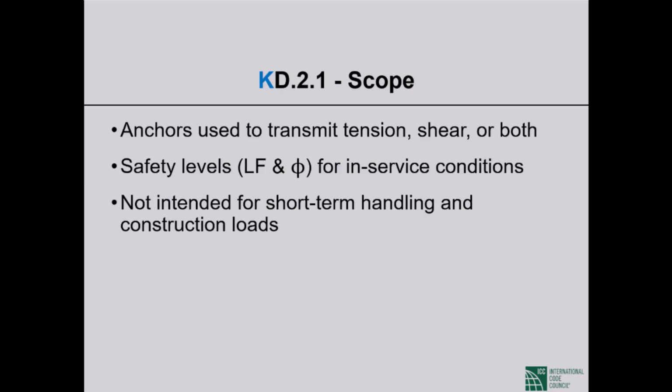The load factors and the strength reduction factors that we use in Appendix K consider in-service conditions of the structure. The appendix is not intended for use for short-term loading and for construction loads. This is very, very important.